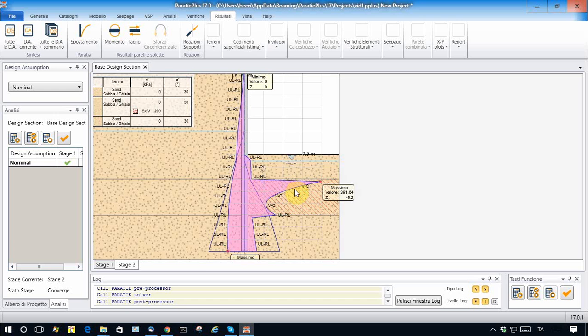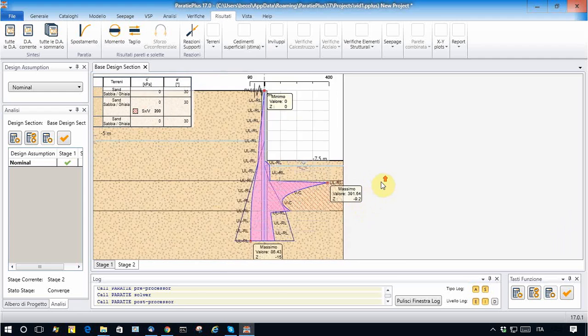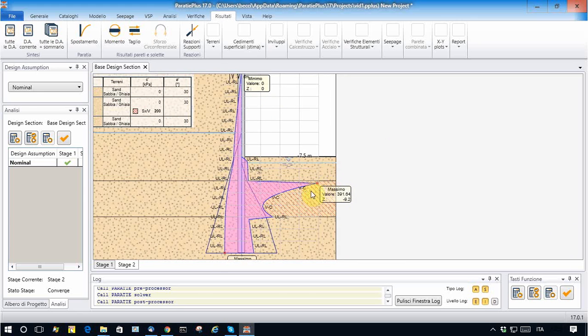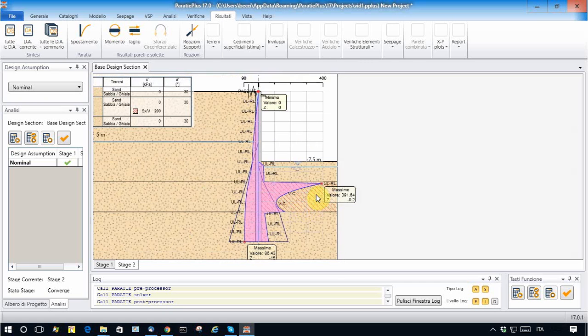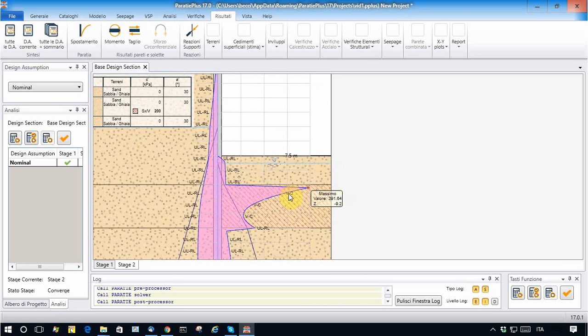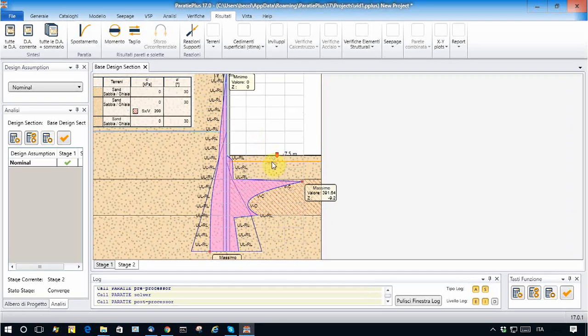Normally, a designer is requested to find the best solution for doing a plug, and this comes from a compromise between reducing the thickness, or in other words the volume of the improved soil, and reducing the bending moment effect, while keeping the safety with respect to uplift at an acceptable value.